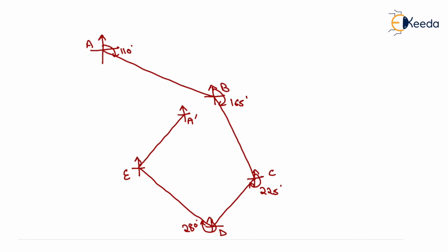Now that is the closing error, which is shown here by the green pen, that is this line, and this line is known as closing error E. This vertical distance is the net sum of latitude and this horizontal line is the net sum of departure. Theta, which we calculated as 28.2 degree, is shown here, and the closing error of 30.04 meter is shown here, and it lies in the second quadrant.